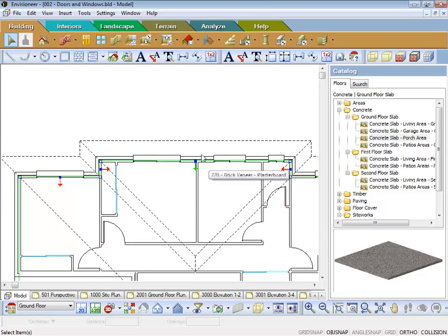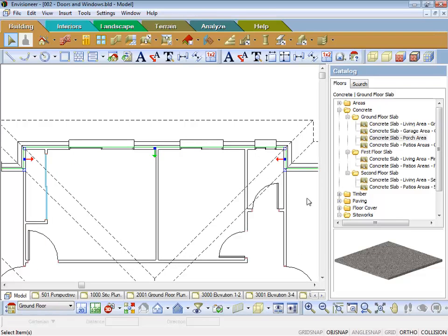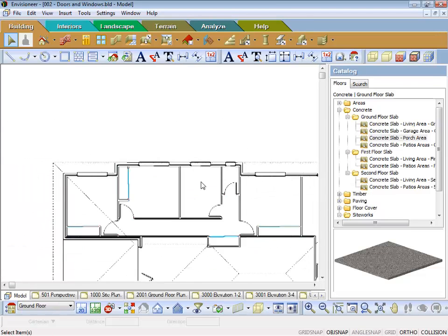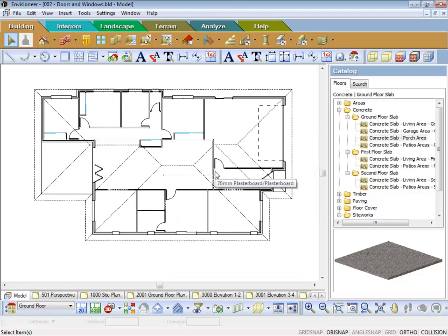Now the edge of the roof that I touched has changed that roof pitching point to green, the others are red, so that's okay. What I want to do now is grab this blue point and move it down so it lines up with this green point over here. Hold the blue down with your mouse, hold your mouse button down, move it over, see how I'm dragging it over to the right hand side, and see how I'm clicking into there. If I get it right and let go, there you go, see how it's just got rid of that. You might have to replay that a few times until you get it, but it's quite easy once you know how. Thank you very much.